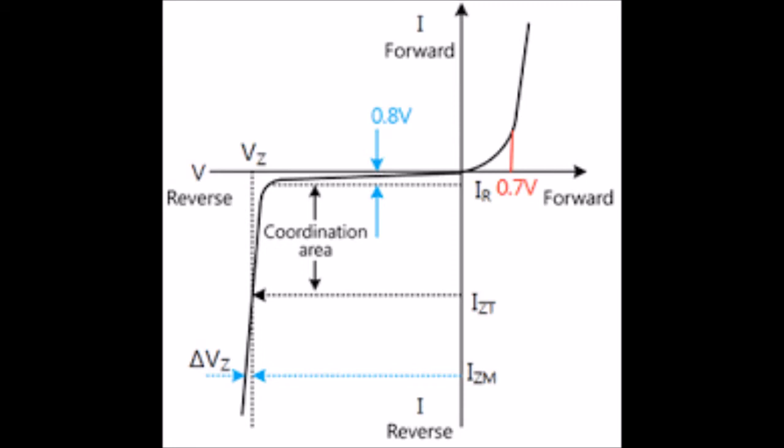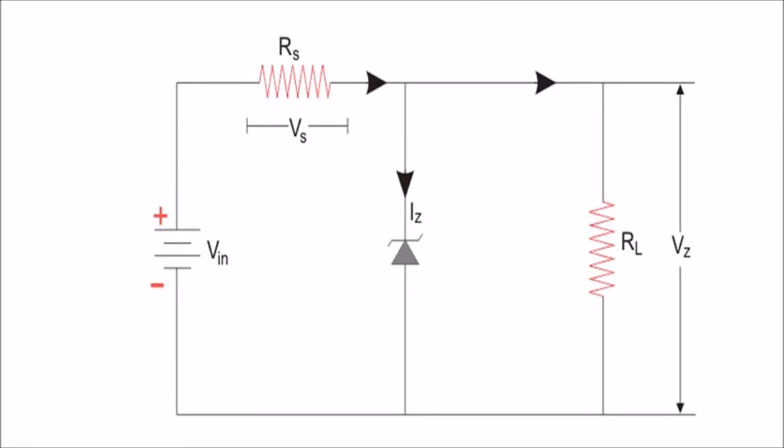For example, a diode with a Zener breakdown voltage of 3.2 volt exhibits a voltage drop of very nearly 3.2 volt across a wide range of reverse current. The Zener diode is therefore ideal for applications such as generation of a reference voltage or as a voltage stabilizer for a low current application.